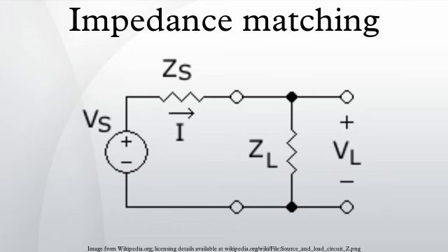The concept of impedance matching found first applications in electrical engineering, but is relevant in other applications in which a form of energy, not necessarily electrical, is transferred between a source and a load. An alternative to impedance matching is impedance bridging, in which the load impedance is chosen to be much larger than the source impedance and maximizing voltage transfer, rather than power, is the goal.